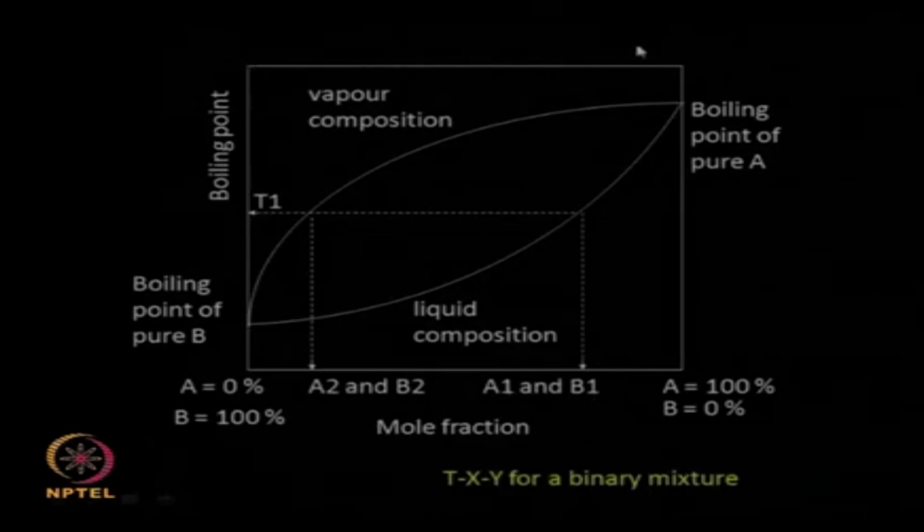So you see, if we have a diagram like this, the TXY diagram, then at any temperature all I have to do is draw horizontal lines and I can tell what will be the composition of A and B in the liquid phase, what will be the composition of A and B in the vapor phase. So this is also a useful diagram.